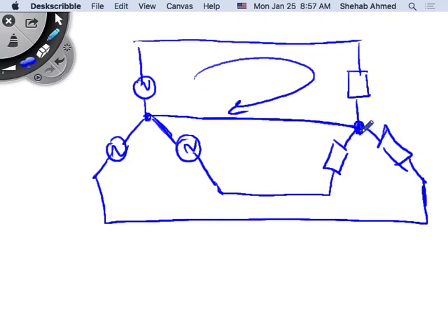These 2 nodes are right on top of each other. There's no current flowing here, there's no voltage drop. So if you do a loop equation, it's just a single loop with one source and one load. That is the beauty of the single phase equivalent balanced circuit, right? So with a star connected system, it's easy.